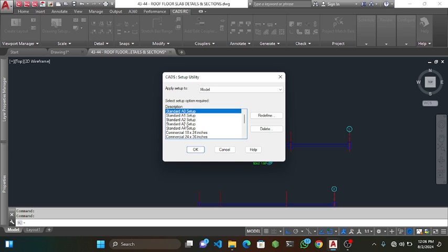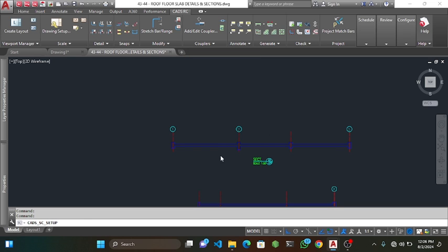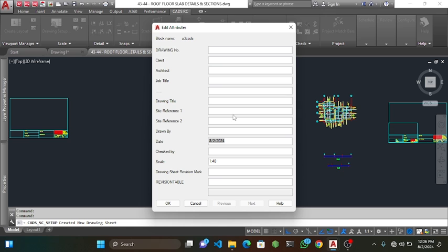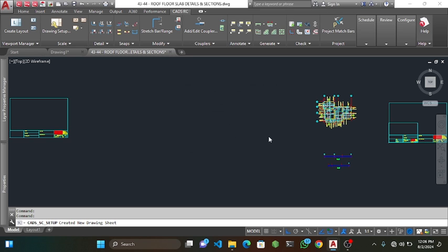of your scale. So let me pick my paper, which is A3. Since I want to use a text height of 100, and I have a scale of 50 there, to achieve this text height of 100, I have to make my scale here 40. If you say 40 times 2.5, it would give you a text height of 100. I'll say okay. So it's asking for a drawing number. I think it was 111 we used in the previous one. Yeah, so let me just give it drawing sheet 2.